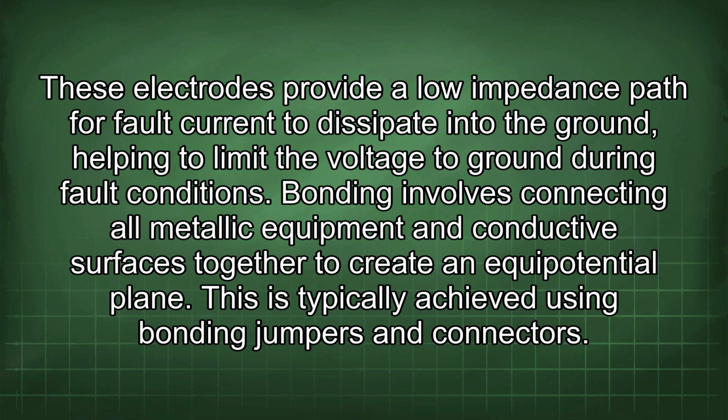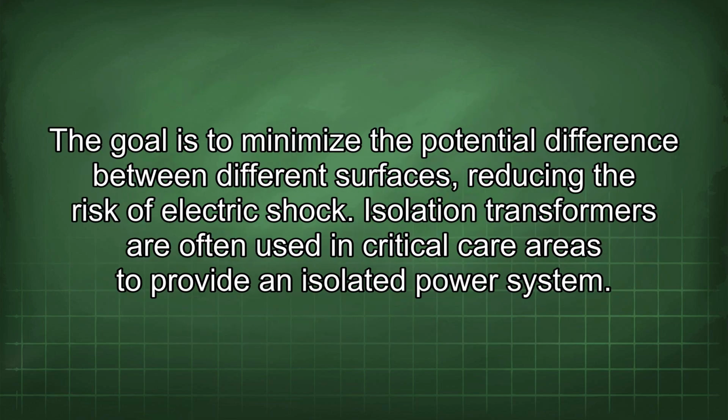Bonding involves connecting all metallic equipment and conductive surfaces together to create an equipotential plane. This is typically achieved using bonding jumpers and connectors. The goal is to minimize the potential difference between different surfaces, reducing the risk of electric shock.